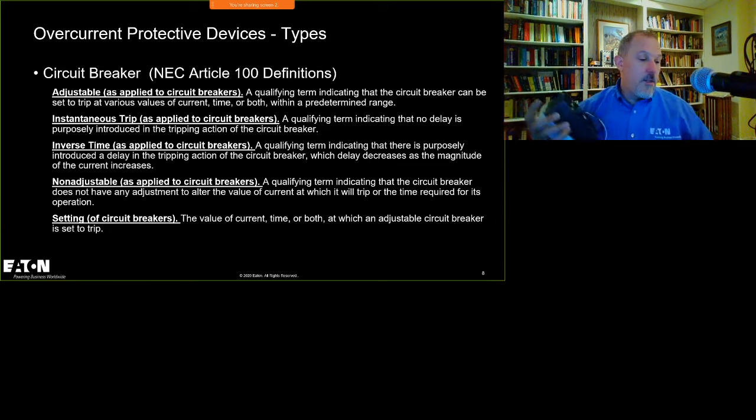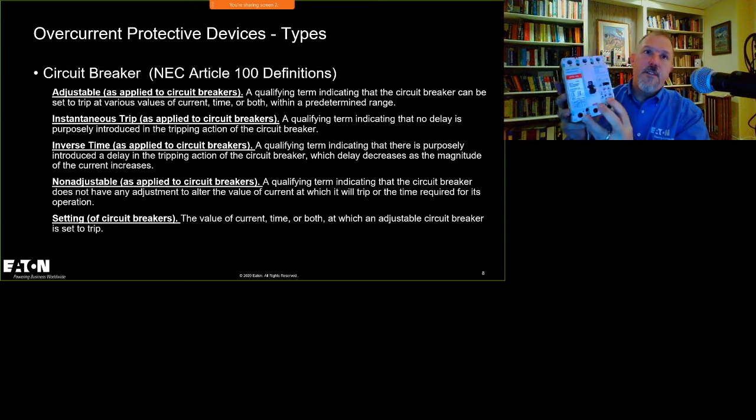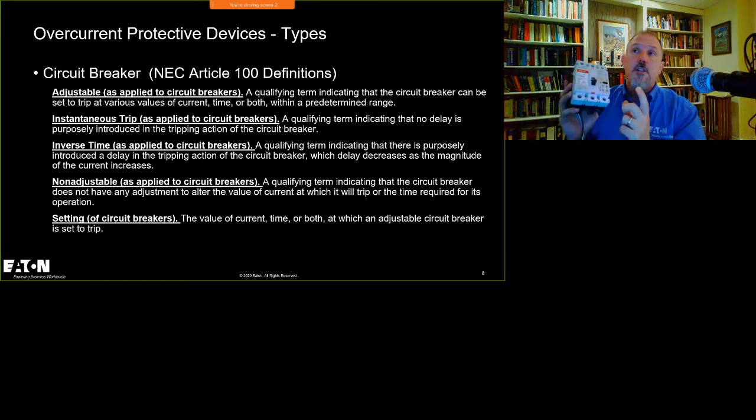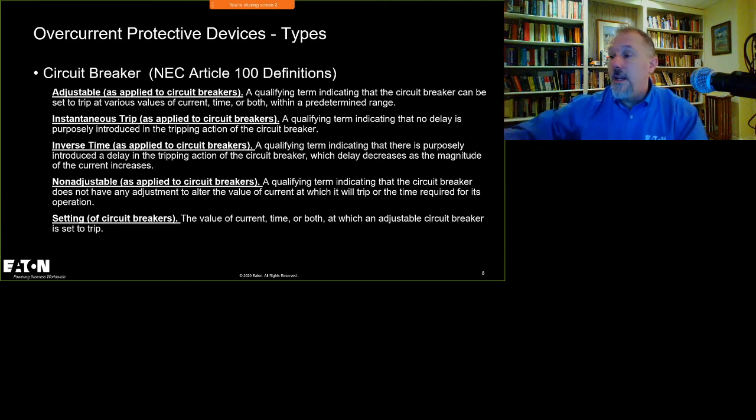Now, when you look at some of the larger breakers, they'll have dials on the front of them for the instantaneous. I may be able to change instantaneous. I may be able to change the long time pickup, short time pickup. And if you don't know what those are, stay here because we're going to teach you. And I can adjust what the capabilities of those circuit breakers are. And that would be your small thermomag breakers. On the larger breakers, we actually have trip units, which we'll cover, that have a lot more functions and features.